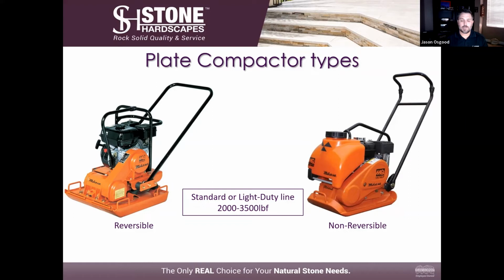So I can run that plate compactor straight over to one side of the deck, flip the handle, and just run it back the other way. With a non-reversible, the vibration center is a little more towards the front, and it pulls that compactor forward. You're not going to be able to reverse this. It's going to fight against you. This one is very good if you've got a big open area and you can make circles and you can turn it.